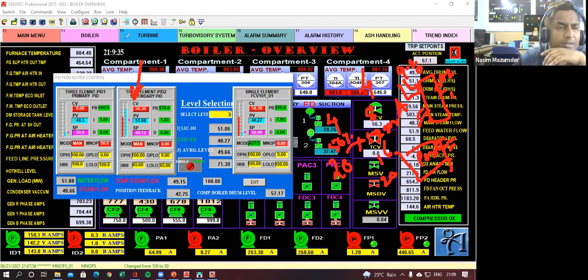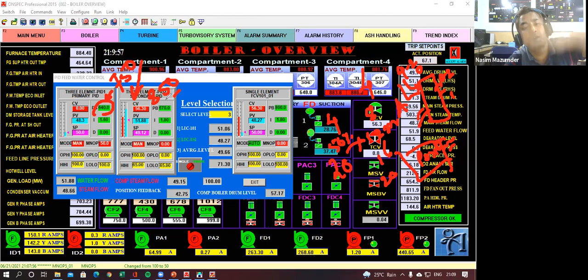You just give some set point over here. Suppose 640 is not working, try for 750 or 740. Make it large or give it 850 and check what is the response of your controller. If it is working, then okay, well and good. If it is not working and the fluctuation is more, then try to close the band. Then you give 750 and check how much variation.